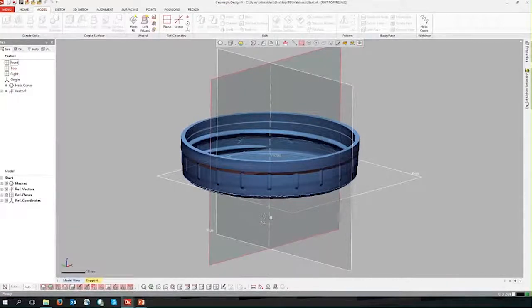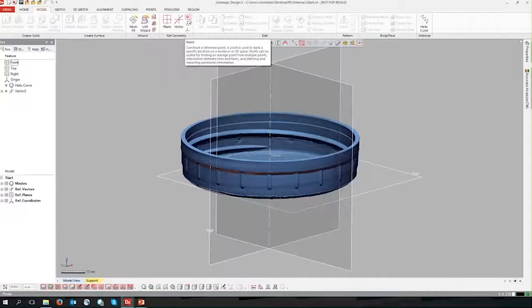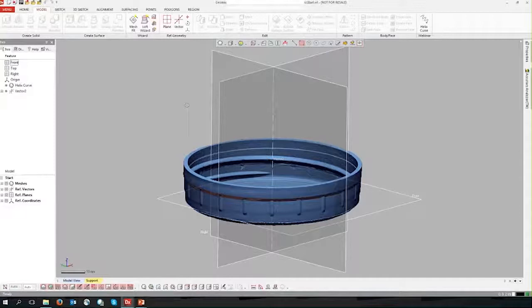There's one other thing we need to start our helix, which is the starting point. The helix can have a reference point, just a reference geometry to start our point. But another trick to use this tool for is to actually get a sketch point to be your starting point. As parts wear and they're used, usually the geometry you're modeling isn't there. So instead of having to find a way to move a reference point from the scan itself to someplace in space, it's easy to just generate a 2D sketch and generate that point there.